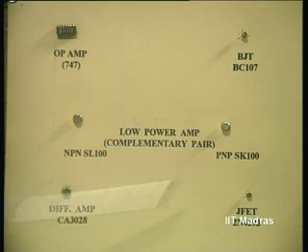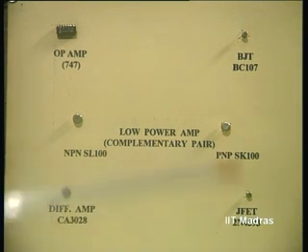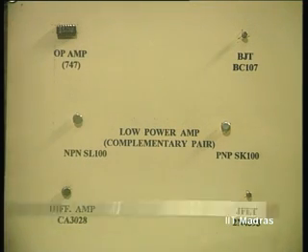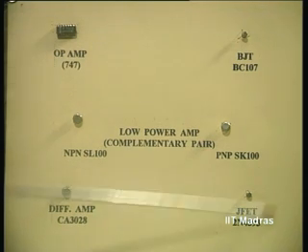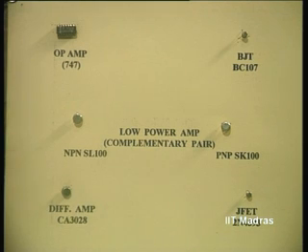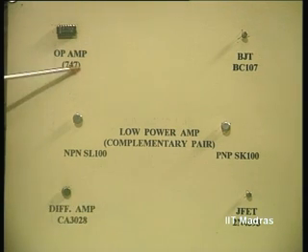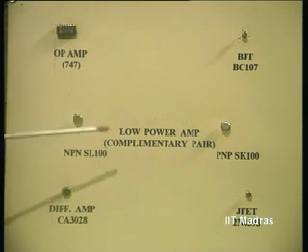This of course is a junction FET. Once again we have 3 terminals, the projection being the source, then we have the gate and the drain. So, these are the active devices which have been displayed here. The application of these, the biasing of these have been discussed, and the use of these in amplifiers we have discussed, and how to design a high gain amplifier and make an op amp out of it has been discussed so far in our course program.